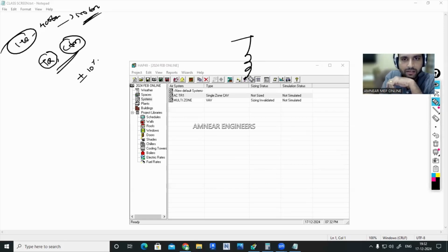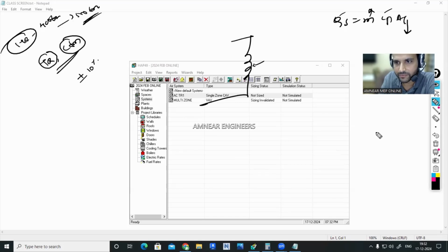See, for example, from the equation itself, we can see m Cp delta T. Sensible coil load is constant, Cp is constant. For the same coil load, m is increasing. What about the delta T? Delta T will decrease. Means instead of our requirement, sometimes we might be selecting a machine with more flow rate, excess flow rate, but the coil load is less.